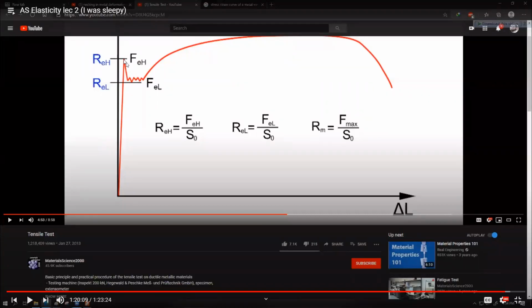a little bit to withstand that force. As a result, the resistive force from within the object got decreased, and because of the same result, the applied force from the specimen also had to decrease, because they both have to be equal by Newton's third law. But the extension was still increasing. The device was continuously trying to pull it apart. I mean, you have to understand this part. We are exerting opposite elongating force onto the specimen to make sure that the specimen continuously gets stretched out.